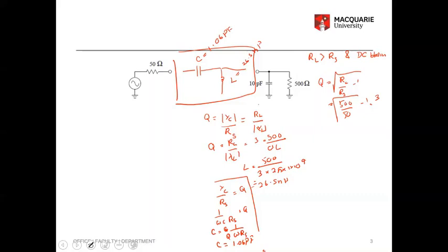When you do this transformation, you only consider a purely resistive load; you didn't really consider this capacitor. Ideally, you would want to cancel this capacitance out with an equivalent parallel inductor here. Basically, we want to cancel this capacitor, which is 10 picofarad, with another inductor in parallel, so they cancel out and it only sees the real part of that impedance. For this inductor to cancel it out, it needs to resonate with the capacitor. That basically says omega squared equals 1 over LC.